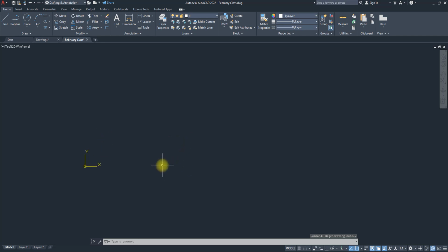So let's look at the first one, which is using the coordinate system. We'll start with the L shape. Before we even do anything, we will have to look at the first drawing tool we have, which is line. So this is the drawing tool, line. If I click on line, you notice AutoCAD tells me to specify first point. The shortcut for line is L. So it's asking me to specify first point.